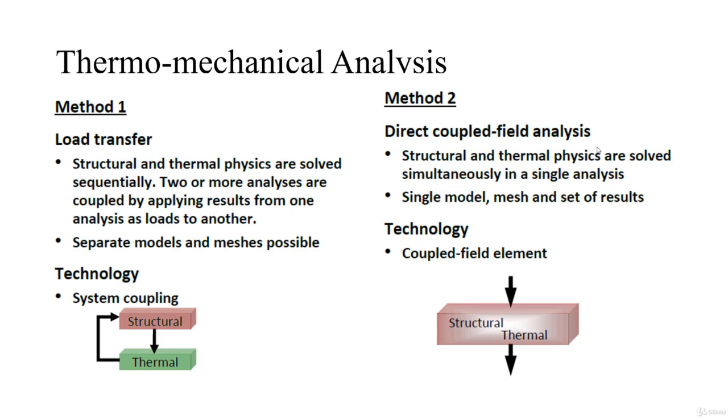Coming to method 1, load transfer, structural and thermal physics are solved sequentially. First we are going to solve the structural problem, then we are going to deliver it to the thermal system, and once we solve the thermal system, we are going to get those results back onto this structural system as shown here. Two or more analyses are coupled by using results from one analysis as loads to another, and we should be using separate models and meshes if possible.